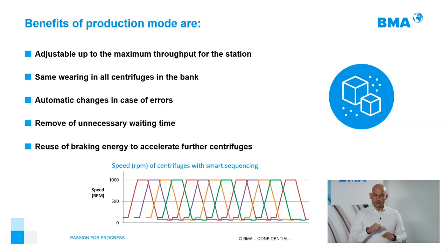We are reducing the braking energy to help the next centrifuges, which are accelerating, giving some energy. That will mean that we will have a reduction in our current consumption, and for this reason, we will also have a reduction in the peaks of energy consumption.